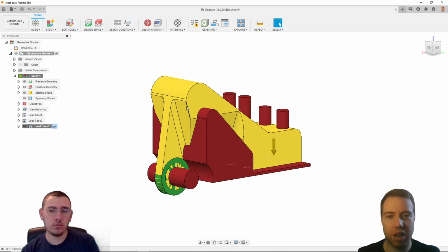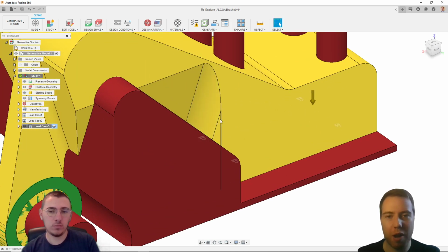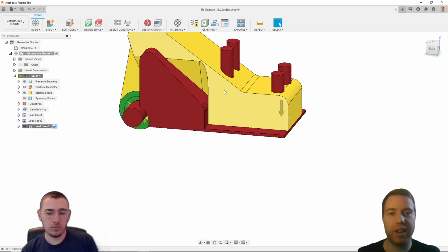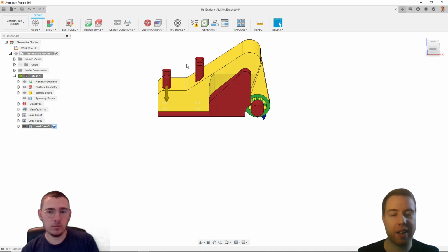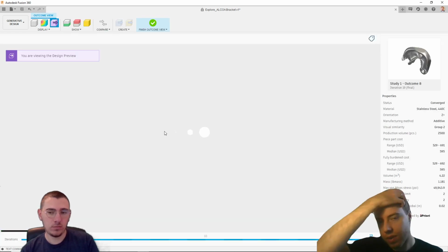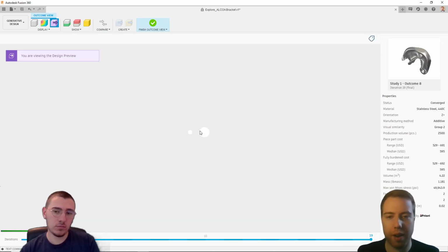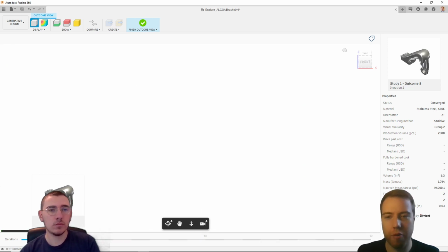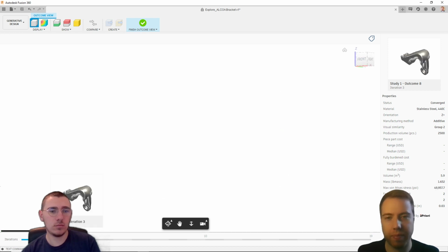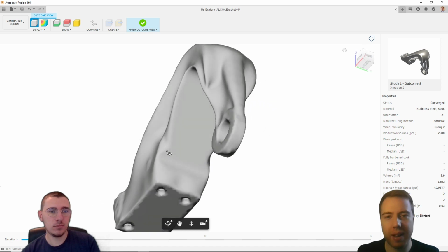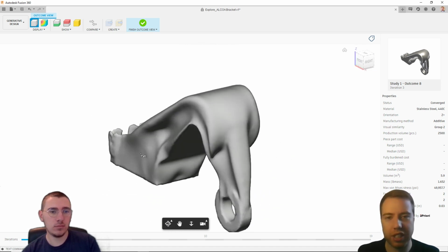So when you create these starting shapes, you can see we've got quite a bit of detail in here, and actually none of that is really necessary. Once generative design has this starting point, it's not necessarily going to follow it at all, and the final design it comes up with might look completely different. So if we go back here, again, we can loop back through these iterations. We can see we gave generative design this starting shape like this. And very quickly, here we can see it's kept lots of those similar ideas.